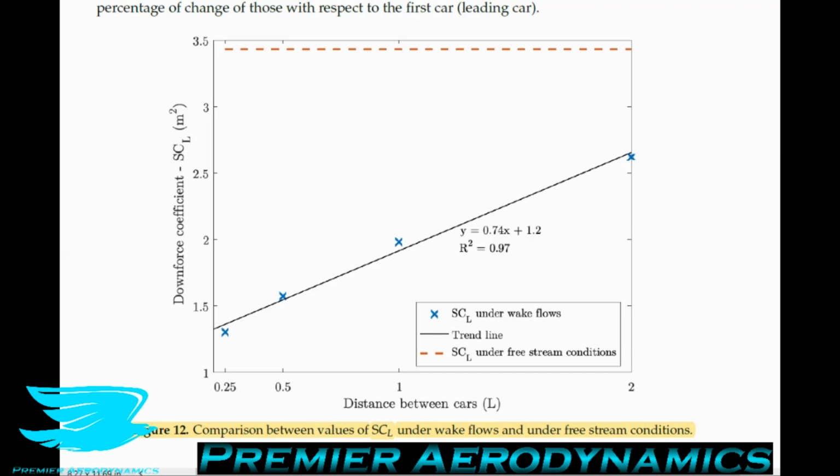Not exactly the coefficient. The lift area is the lift coefficient times the cross-sectional area of the car, which is a measure of the lift that's being produced by this particular car. And all we need to do is multiply it by the dynamic pressure to get the lift in total.